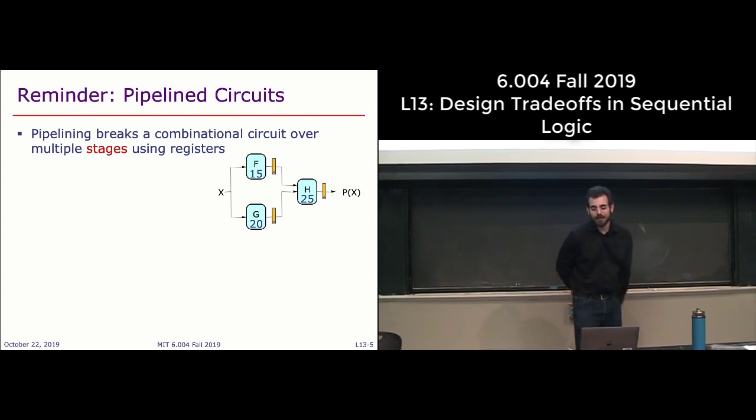Well, the propagation delay of each component is given in the component itself. So you have 15 nanoseconds, 20 nanoseconds, and 25 nanoseconds between these registers, right?